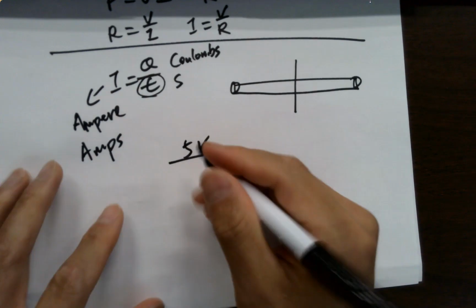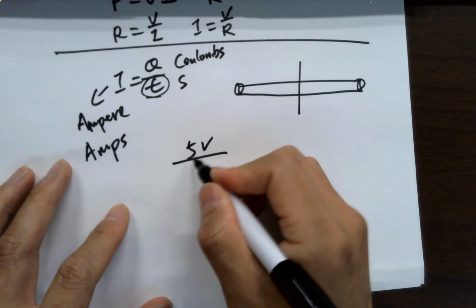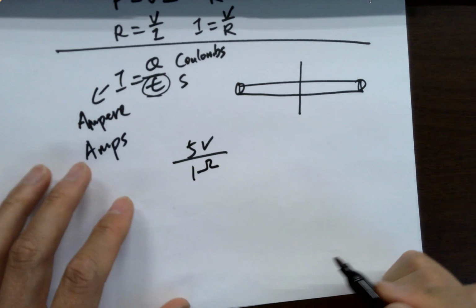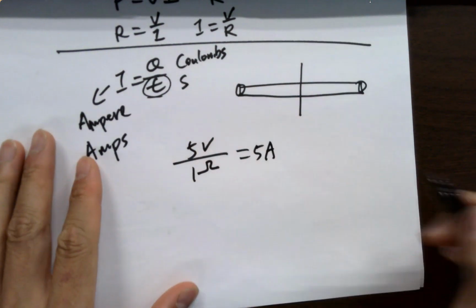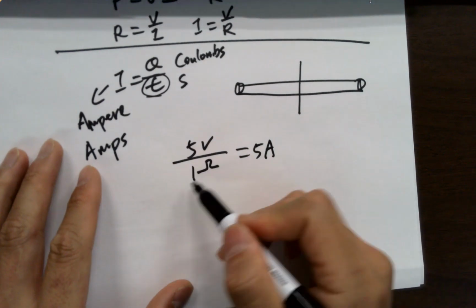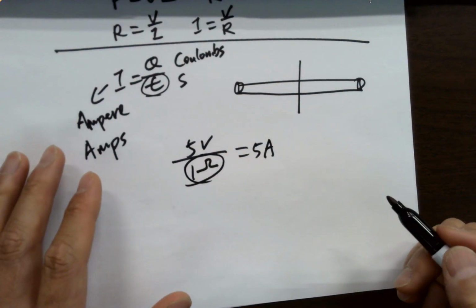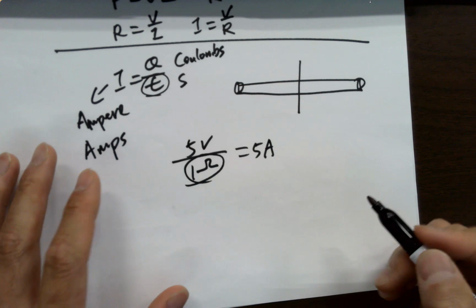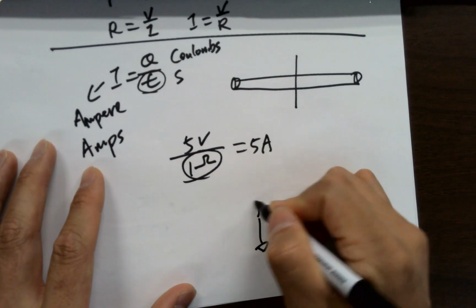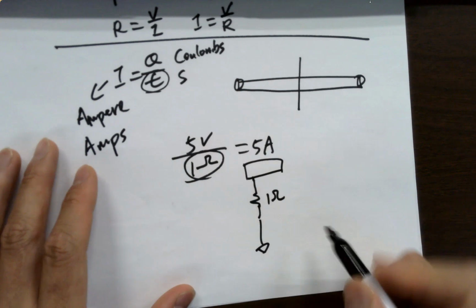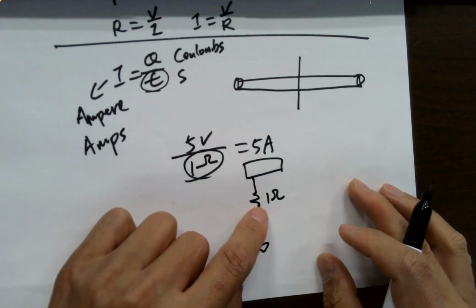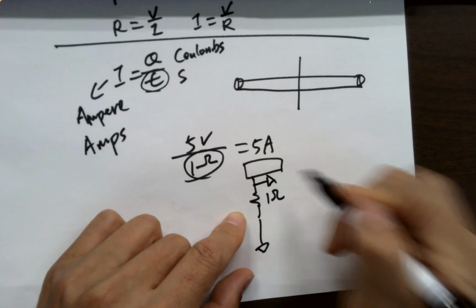Okay. So for example, if I do 5 volts and 1 ohm, who is going to do that? It's going to draw like 5 amps. And 1 ohm is not doing anything really. It's very similar to a short circuit. If you short 1 ohm over here to the ground, the whole circuit is not even able to notice that. It's like treating this guy as a ground.